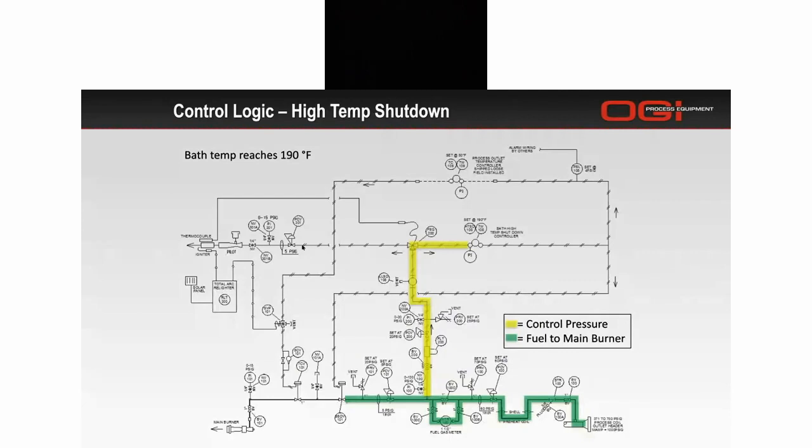This is also a reason why you would want to have a pressure switch. So you can see that upper right-hand corner. It's kind of hard to see, but there's that PSL 108 that we saw that was mounted to that saddle. It's set at 4 PSI. So it'll trip. It'll give a signal. In this case, it lost pressure. So under these conditions, it's going to sense a fault and give a dry contact, either open or close, to remote operators, to say, hey, something just happened. The heater shut down for some reason, and then it can be investigated from there.